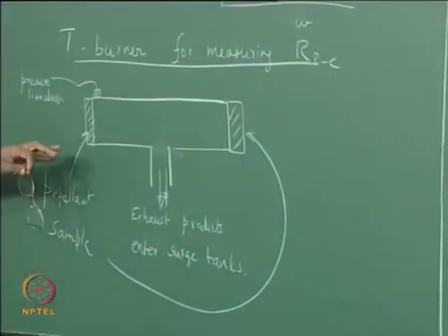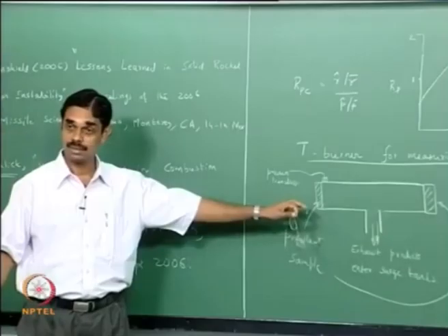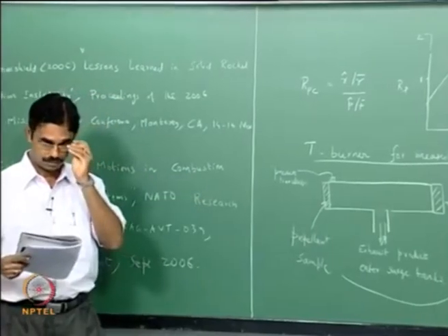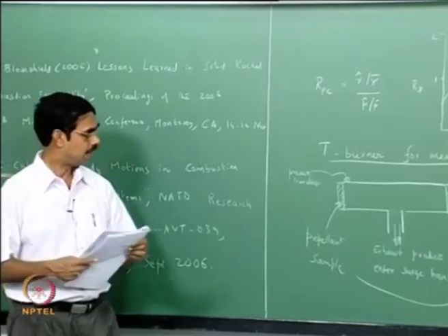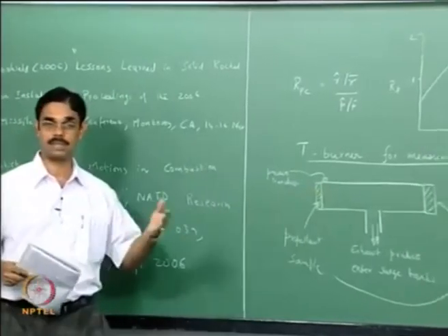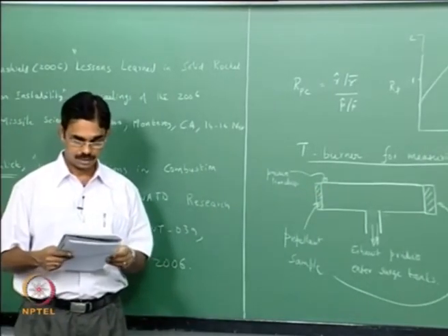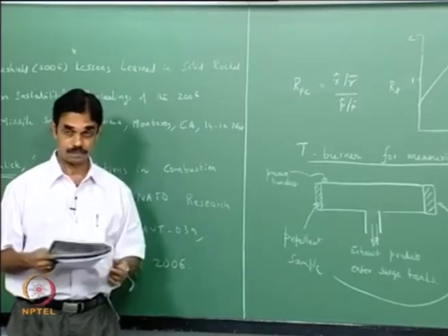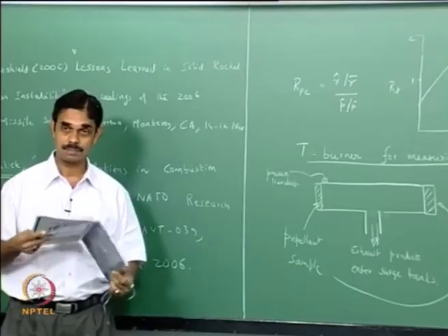The reason for mounting the pressure transducer near the end is because pressure is maximum there, whichever mode it is. And you pressurize it to begin with so that we can get the right mean pressure. So when the propellant burns, it will shift, right? What will shift? The end.